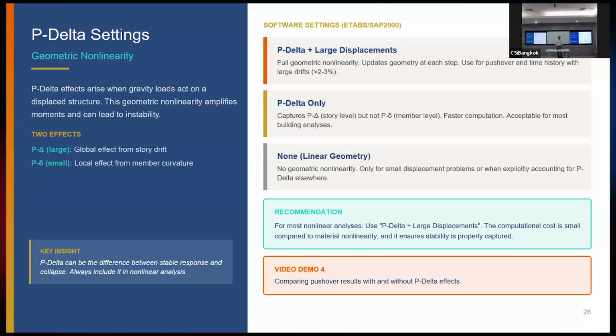So that means the stiffness will change drastically from being an arch, which has a lot of stiffness as an arch. But if the deformation becomes very large, it will become flat, very thin as a beam, it will have no stiffness. And then if I bend more, it will become like a cable. It will again have stiffness. So this is called a snap-through problem in nonlinearity. So this is the line.